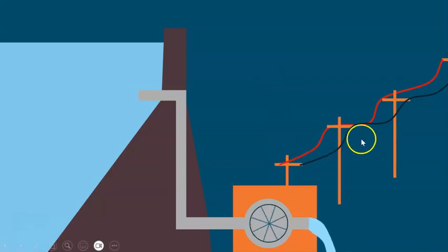If I start drawing electric power away from my turbine over here, I have to be taking energy from the water, so therefore I must be applying some resistance to the water flow. So water's flowing down this pipe, I'm taking energy away, so therefore I'm resisting the flow, decreasing the flow somewhat, and I can capitalize on that energy, that power, and take it away as electricity.